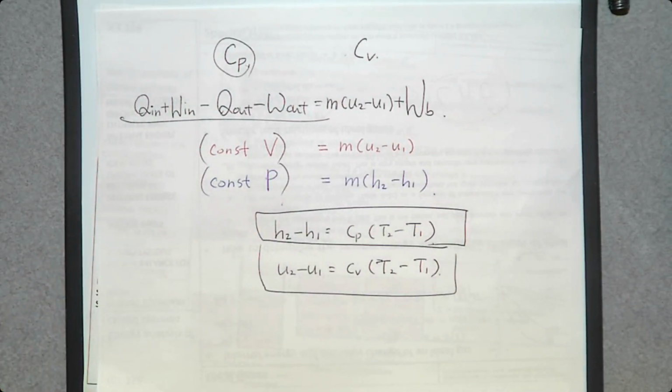Do we need to determine the phase change process at the initial state and also at the final state to evaluate U1 and U2? Not anymore. As long as you have a pure system, you can guarantee that there is no phase change. It's just gas or liquid or solid. Then you can use specific heat.